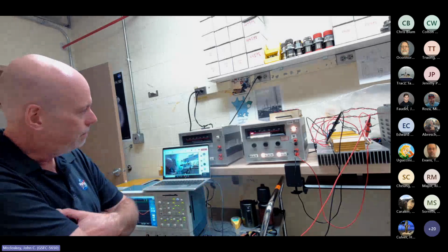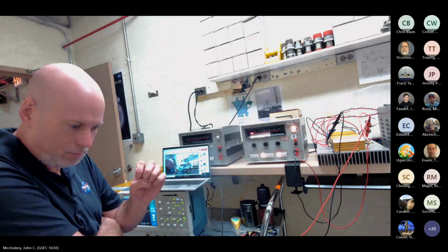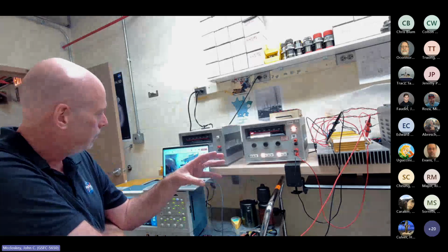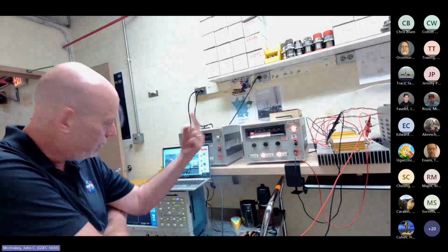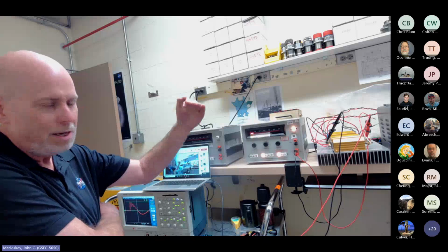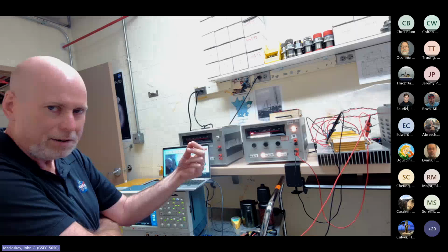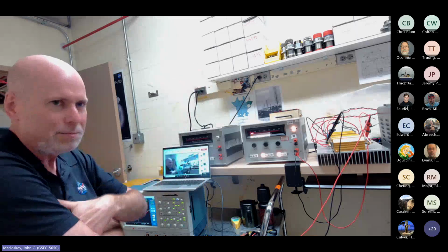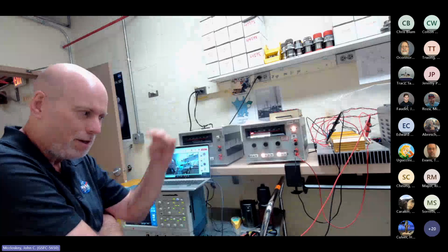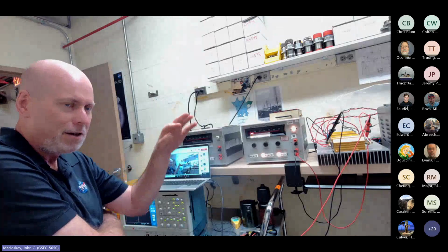I think when the default was 28 volts, and then we would apply a 28 volt transient, we're going up to 56 volts. Your front end components might see 56 volts. But then when we've gone up to 30 and now doubling the bus potential takes us up to 60, I think there have been some cases where that went beyond a threshold. Some parts were on the hairy edge there.